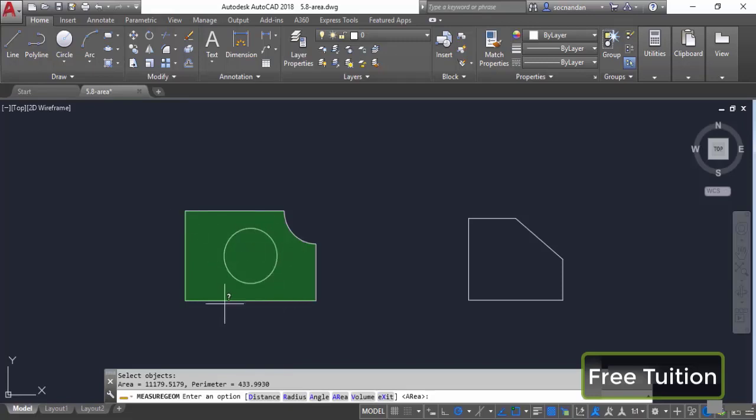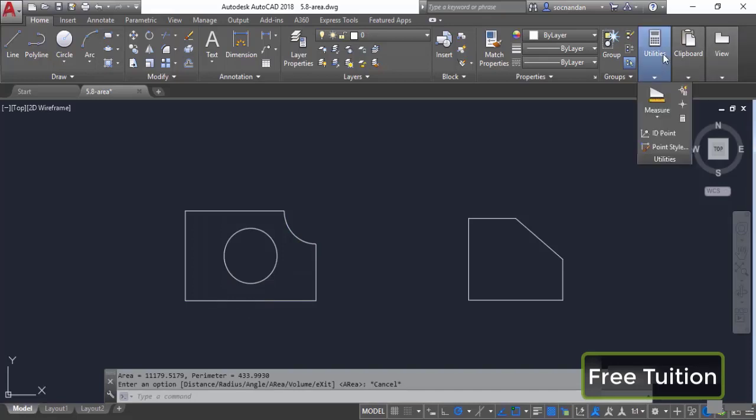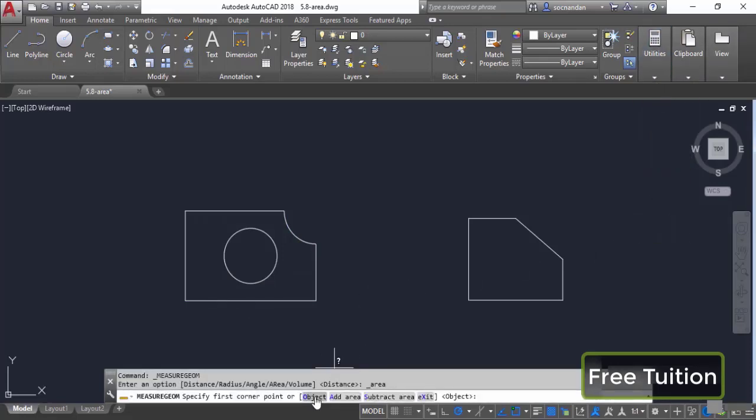In those cases you can use the subtract tool. So let's press escape key and once again I'll go to the area. And now look at the command line. So we have some options here like add area, subtract area. So select this subtract area first and now click on object and click on this circle.